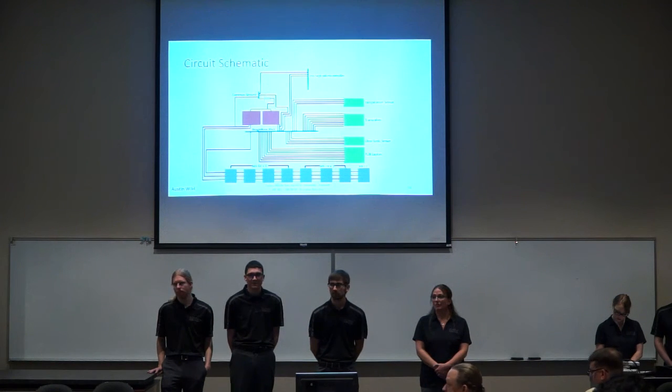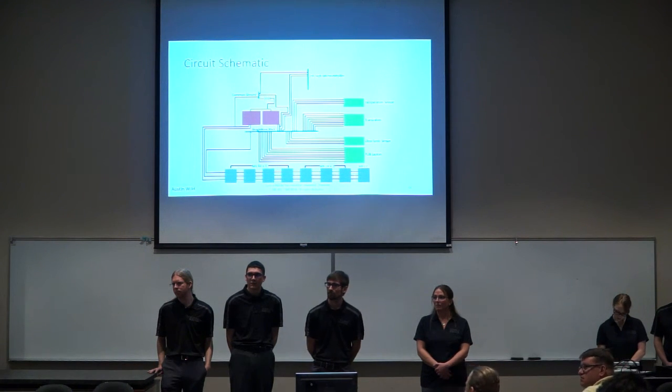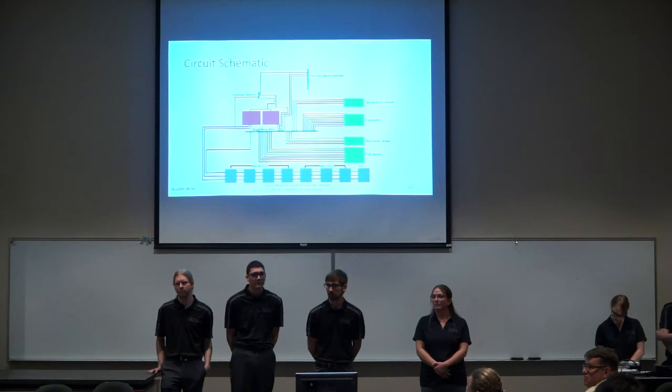One other comment on that one, you've got power and ground that are tied to the BeagleBone Black. My concern is always that people sometimes try to treat their microcontroller as a power supply, which it's not. I'm assuming you have some sort of regulation in the BeagleBone Black that you can grab off of. Is that where you're getting your power for the sensors? It's a board, right? Not a chip. Yeah, it's a board, and so it actually has a power regulator on there. Okay, that was just my concern.